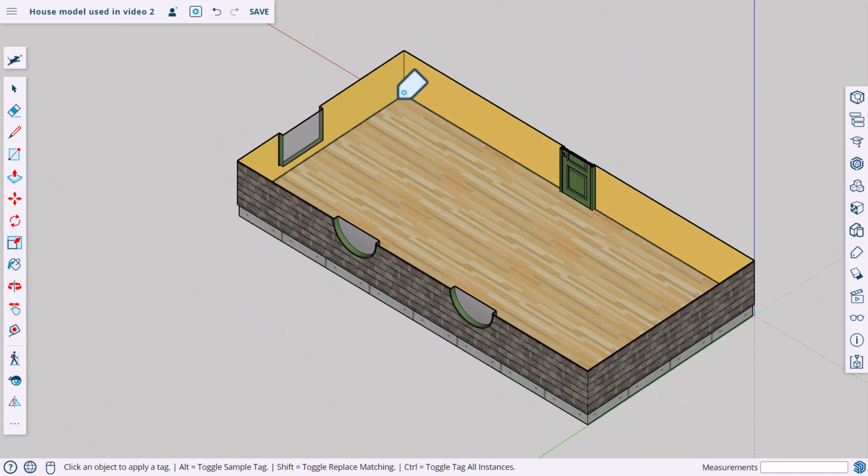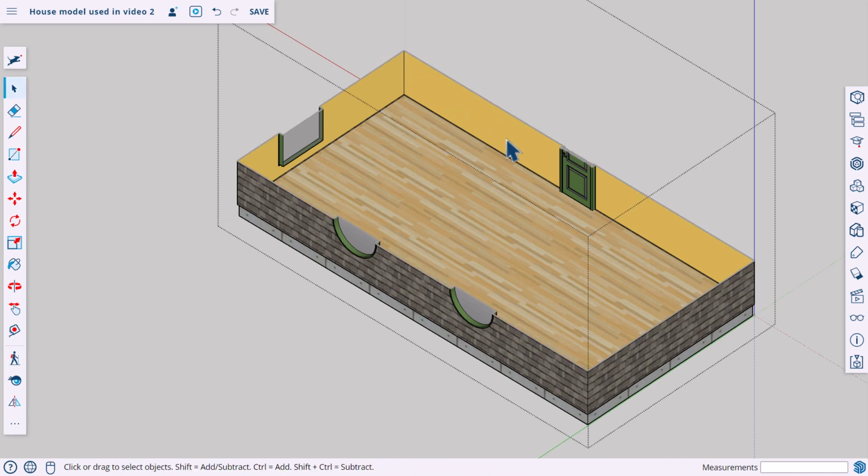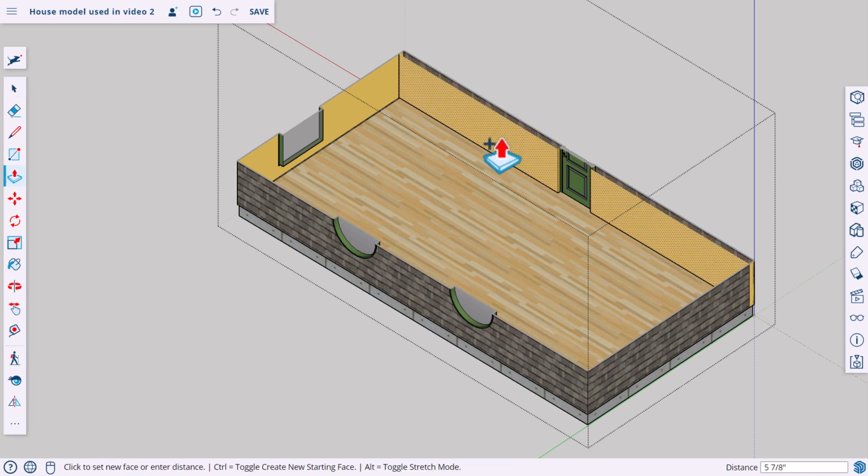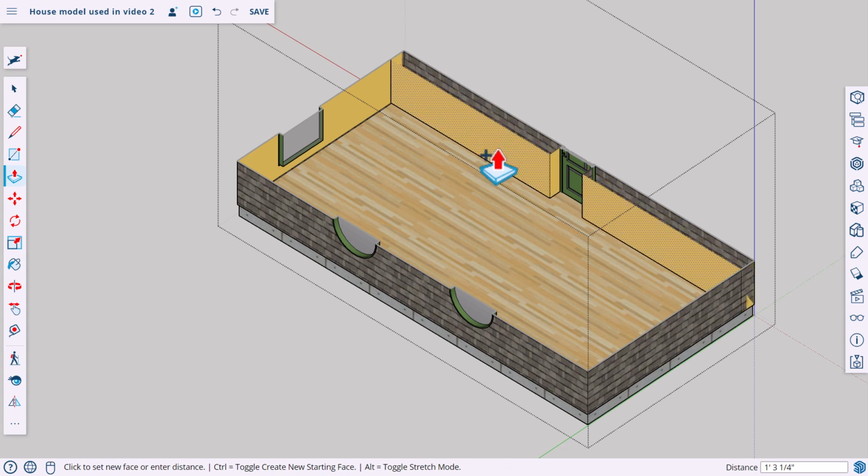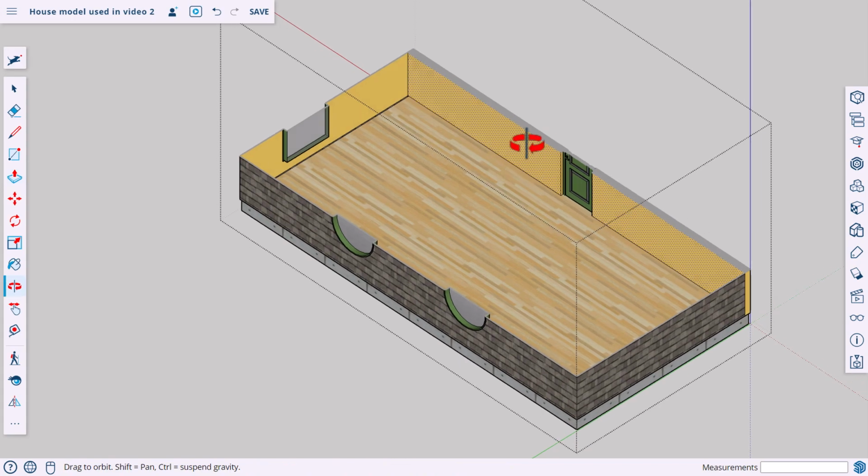These are all basically paper-thin exterior walls. And I could absolutely push-pull this outer wall. Let me double-click on the component first, or the group, to push-pull it, and tap Control to make a copy so that I preserve that exterior wall. And I can push-pull this wall in 6 inches. I'll just tap 6 to make it 6.